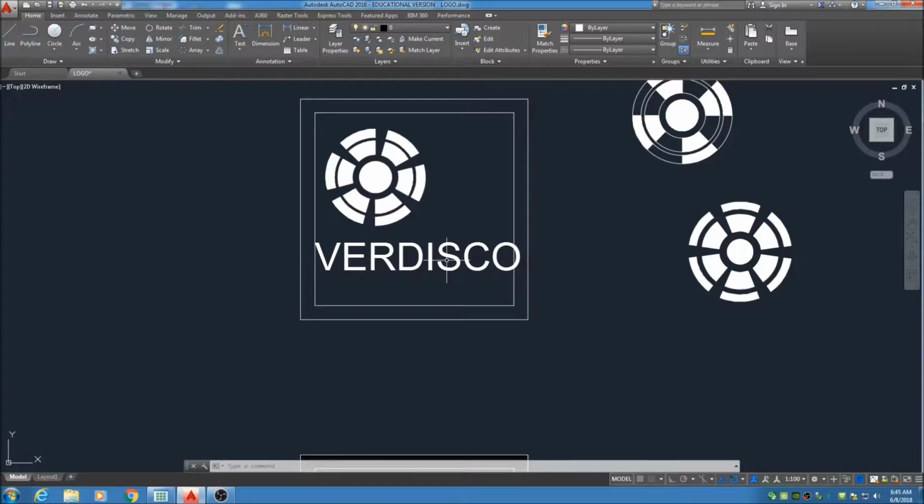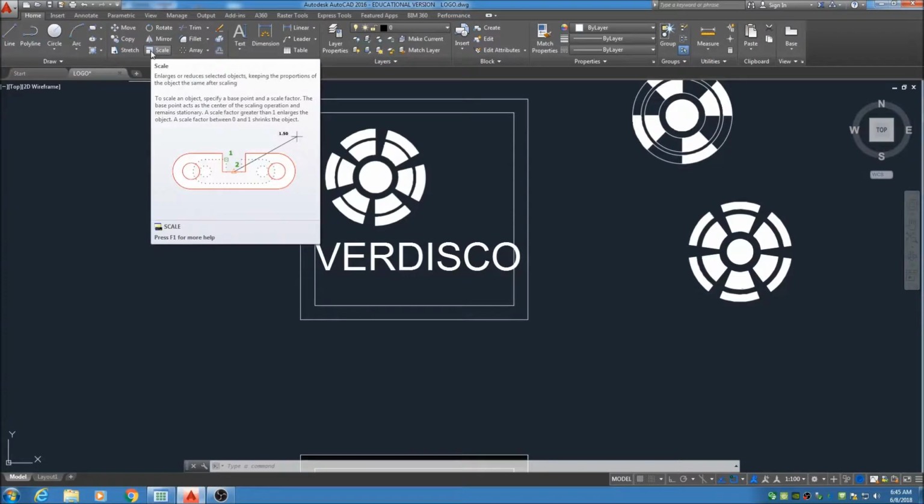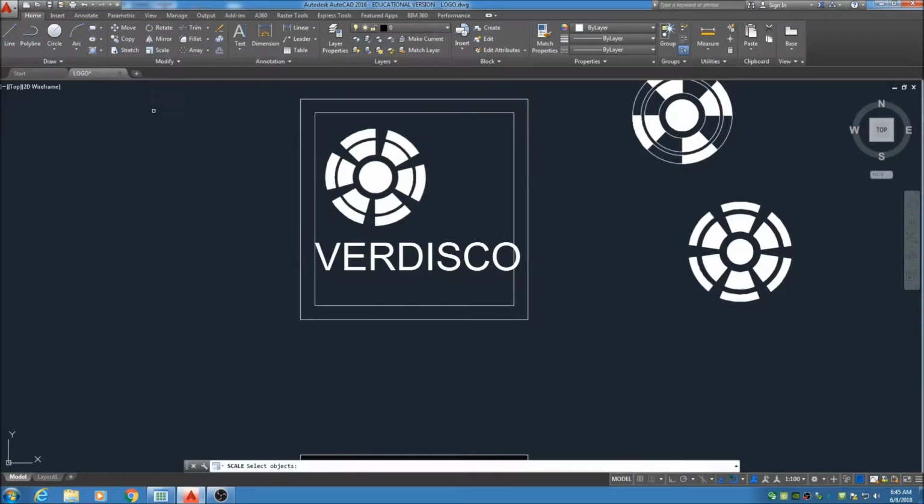Let me show you a little trick. Here's my excuse to show you the scale tool. That's right, the scale tool. I'm going to select the scale tool. The command line says select object, so here's the object I want to select. Space bar to get to the next command. Now we float over here and click. And now I'm not holding the mouse wheel down. I clicked and released. If I very slowly drag this way, I can size out manually. Just like that.